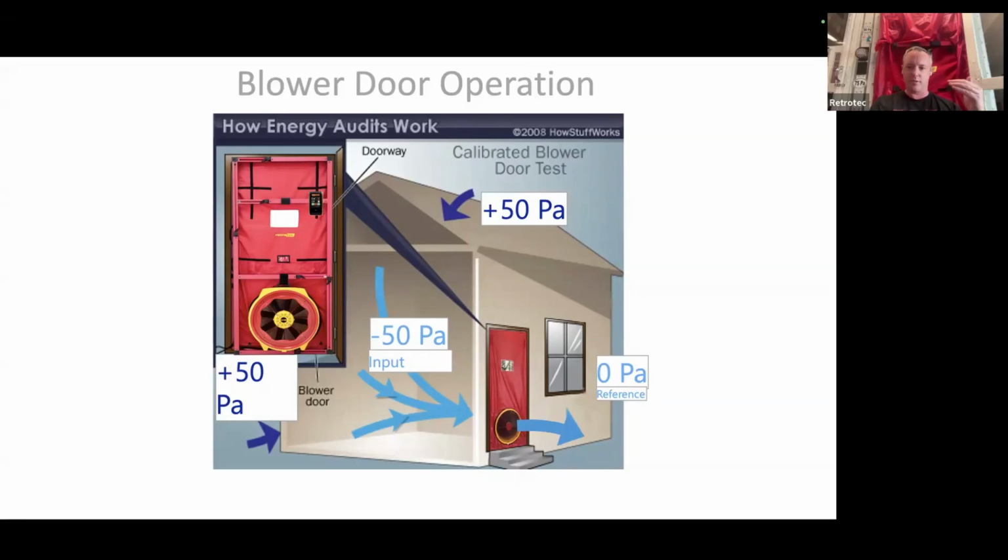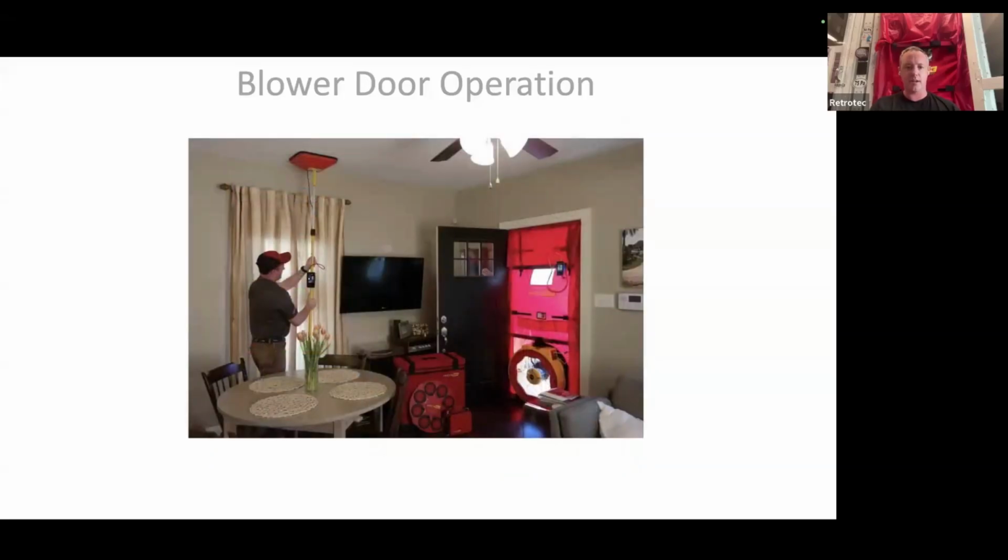Wherever the air barrier is, the ceiling, the roof, it's going to be positive 50 right along that edge. If you're doing some probing, like I talked about earlier with another manometer, or if you're using a pressure pan, you're going to be reading a positive number because that's air coming into the building. So this is what a pressure pan looks like if you've never seen one.